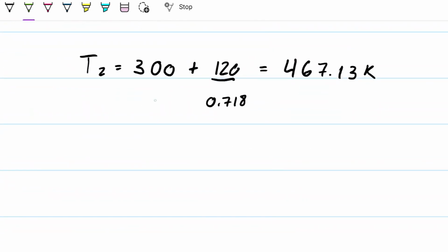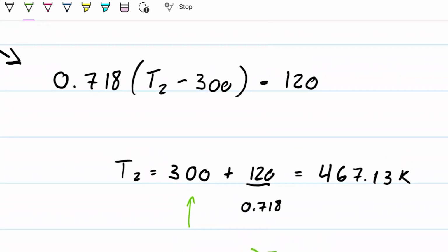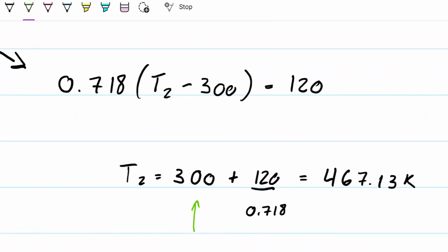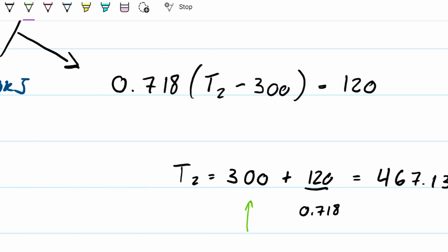All right, now let's look at units. We have Kelvin, here we have kilojoules, and we're dividing the kilojoules by kilojoules per kilogram Kelvin. All right, so we have a problem here. Oops, we want it to be in Kelvin. What we actually have is kilograms times Kelvin. Okay, so we don't have the units right. So that means I'm going to go back one step, and we're going to see that over here, I need to be multiplying it by the mass.